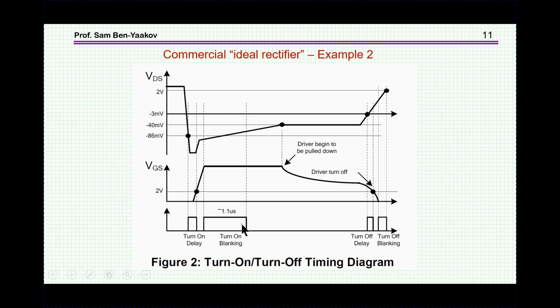Now there is a delay here, which is very good, a blanking delay in which nothing will happen. It will not reverse the situation. This is very good against spikes and parasitic oscillation, especially in DCM. I'll talk about it a little bit later.